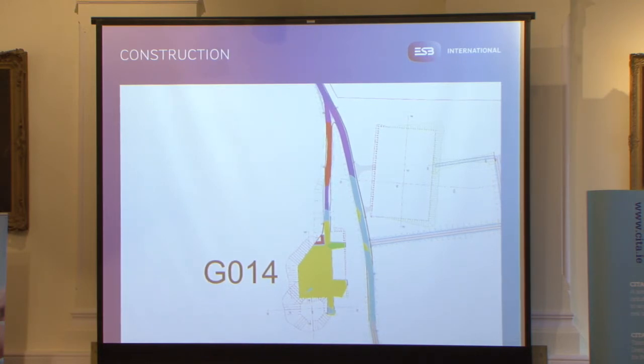As the project is being constructed, we can take back as-built information and we can input these into the model in order to establish that it's been constructed as per design. We can also use it to identify any areas which might pose problems in the delivery of the blades to the site. We can do a level comparison and identify any areas which might pose problems for vertical alignments for the turbine delivery vehicles.